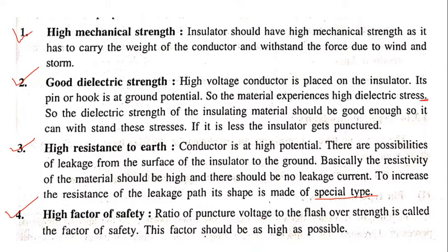Then the fourth one, that is high safety factor or high factor of safety. The ratio of puncture voltage to flashover voltage is called the factor of safety. This factor should be as high as possible.